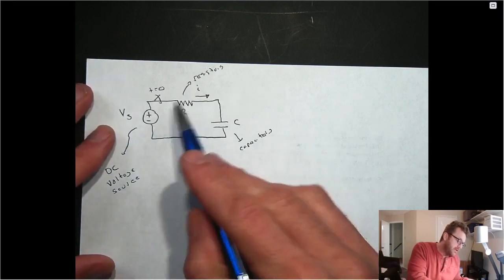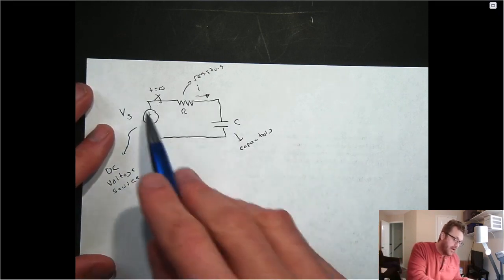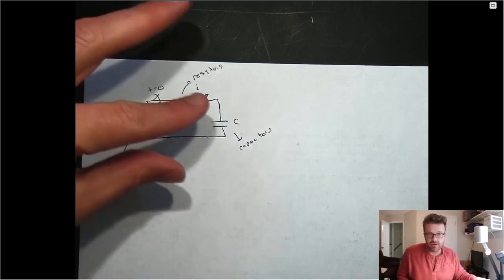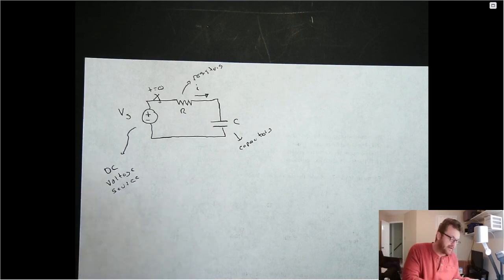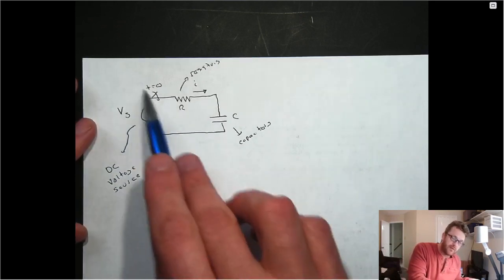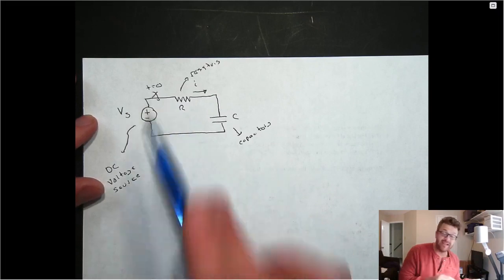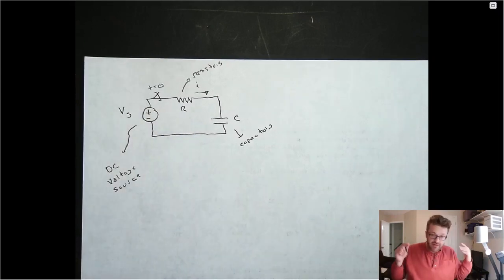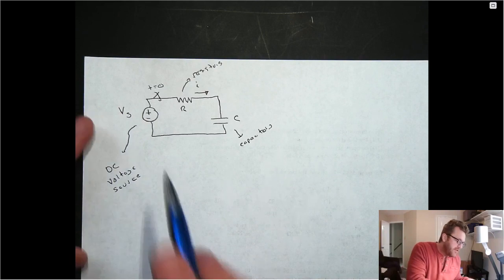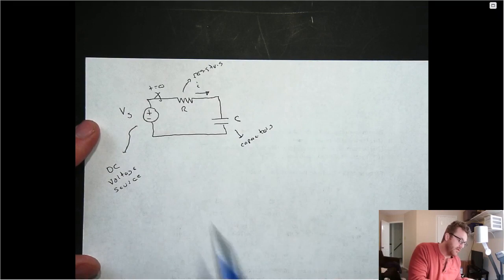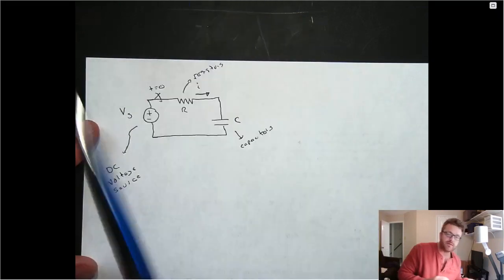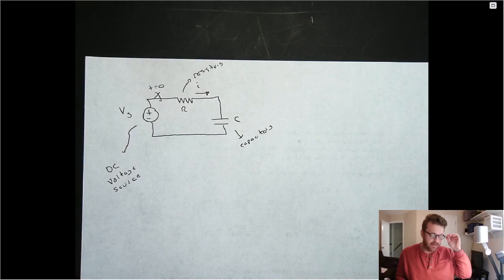So what happens, in terms of the current in this circuit, if you put a DC source, meaning the polarity of the push never changes, is that you're not going to have a long-term current in this circuit. Basically, enough charge is going to move through the circuit after the switch is closed, and the switch is doing nothing more than giving us a context of the time at which our simulation is beginning. But after that switch is closed, all that's going to happen is enough current will flow to charge up this capacitor until the voltage across the capacitor equals the source voltage, and then everything interesting in that circuit is done. And that initial period of charging the capacitor is called its transient period.